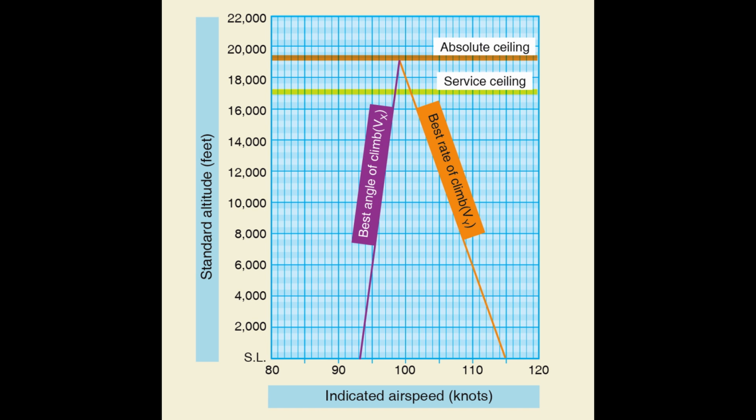On airplanes equipped with an independently controllable pitch propeller, this requires advancing the propeller control prior to increasing engine power. Some airplanes may be equipped with cowl flaps to facilitate effective engine cooling. The position of the cowl flaps should be set to ensure cylinder head temperatures remain within the manufacturer's specifications.